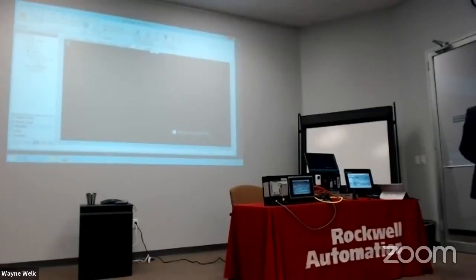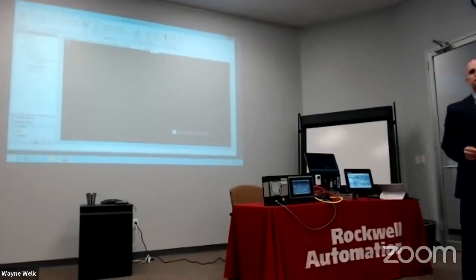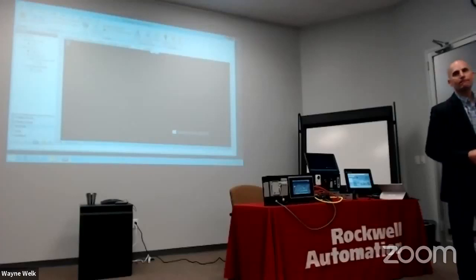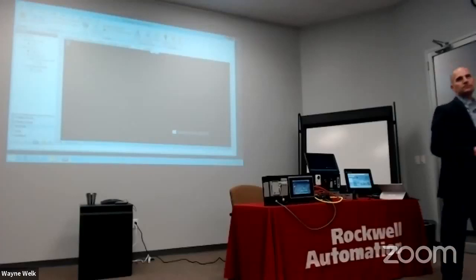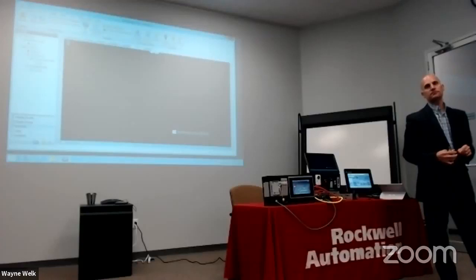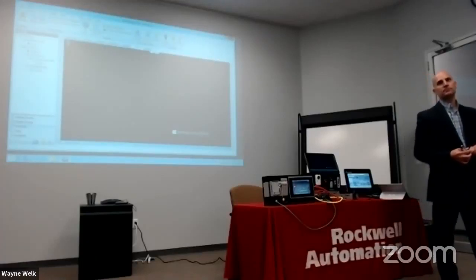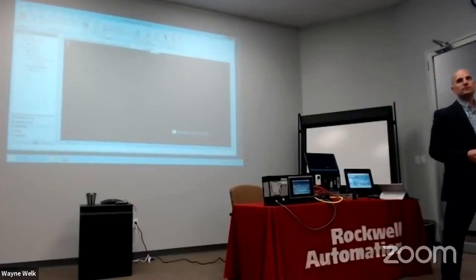So one thing Mike showed that you guys might have missed is the fact that when he logged in with his badge, it had a timeout period on it. As soon as that timeout period ended, it went back to that same client that he had originally. So you guys can program what the read-only or the operator login is. Have somebody badge in for maintenance, administrator. It's all different content with multiple pieces of connections on it. And as soon as you log out, whether that's a timeout period or somebody manually logs out, they'll default back to that one aspect that we're looking at.